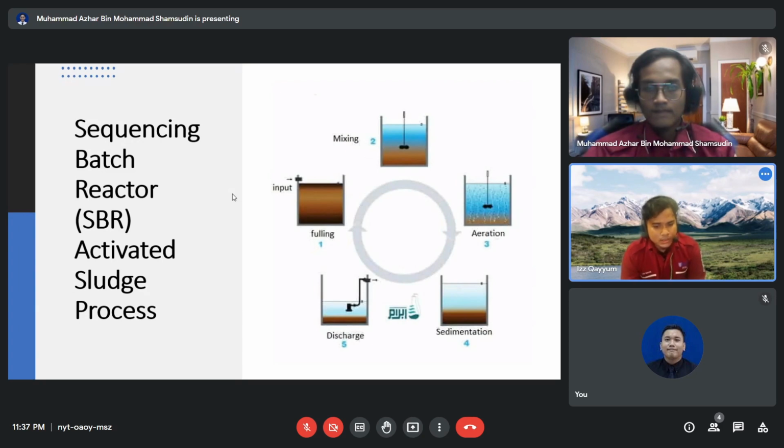Biochemical treatment methods are discussed, as the process removes dissolved matter in a way similar to self-purification but in a further and more efficient way than clariflocculation. The removal efficiency depends upon the ratio between organic load and the biomass present in the oxidation tank, its temperature, and oxygen concentration. The biomass concentration can increase by aeration, but it is important not to reach a mixing energy that can destroy the floc, because it can inhibit the following settling.